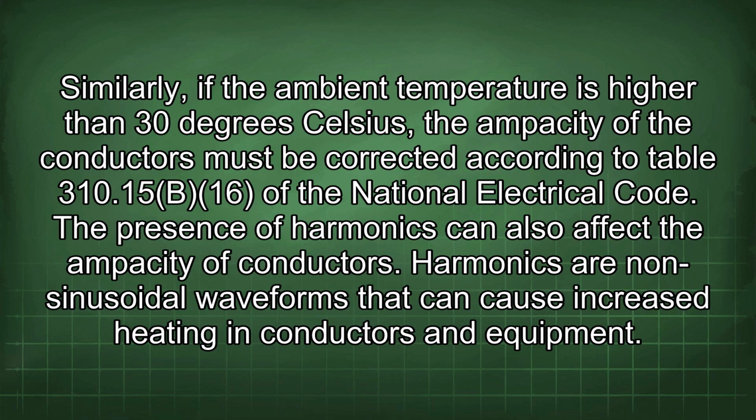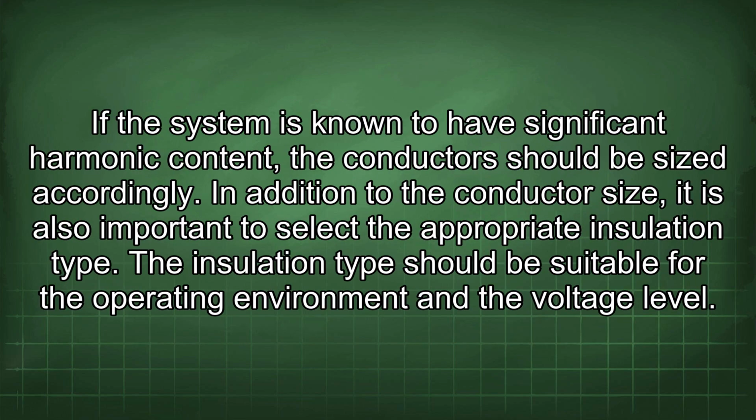The presence of harmonics can also affect the ampacity of conductors. Harmonics are non-sinusoidal waveforms that can cause increased heating in conductors and equipment. If the system is known to have significant harmonic content, the conductor should be sized accordingly.